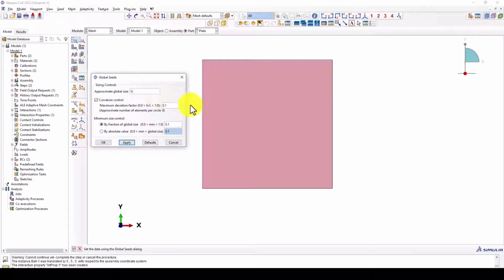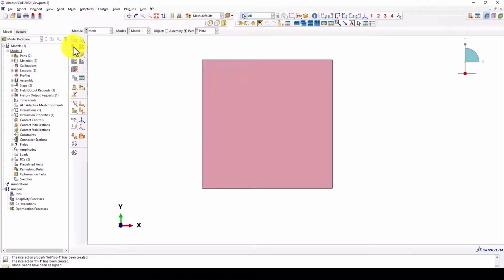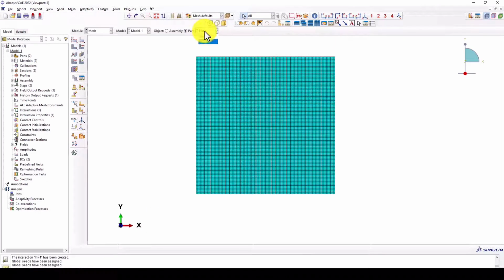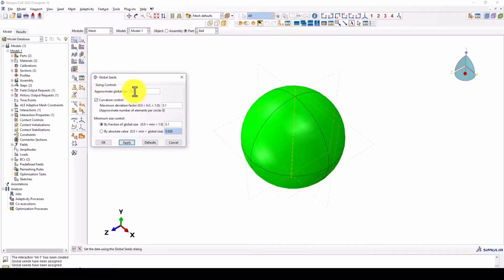We can obviously include thermal strain or we can include the volumetric strain. Thermal strain occurs due to the change in the temperature. We can include that in this particular analysis. We know about the yield point. Material starts to deform plastically at the yield point and stress remains constant or slightly drops while the strain increases. That is known as the yield point.